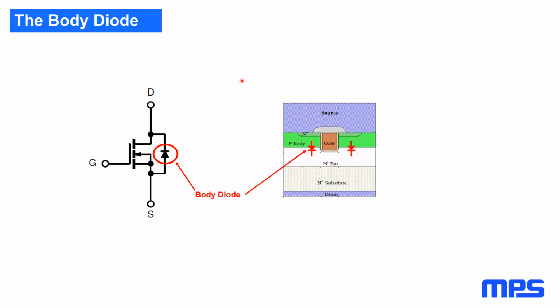Great. Next, does MPS currently offer MOSFET drivers with an active Miller clamp? Yes. A number of them have them. I'd have to look to see exactly which ones do and which ones don't. But the ones intended for higher powers definitely include a Miller clamp, especially the ones with internal slew rate control.